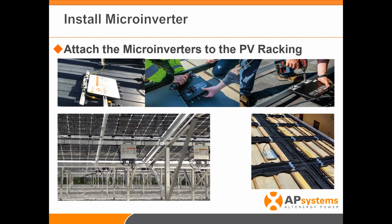Attaching the inverters. One question that we do get asked quite a bit is, what orientation must the inverters be in? And there actually is no orientation requirement. What we do ask is that it's underneath a solar module and that it has at least 1 inch around the entire device. And there's two reasons for that.